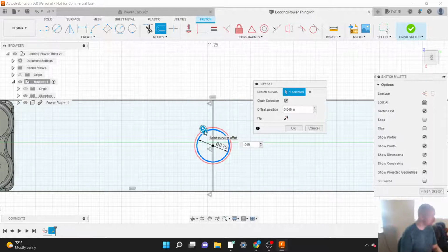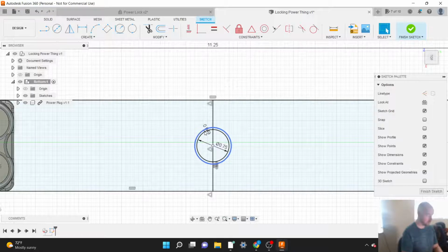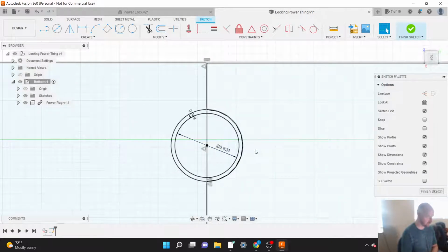Okay, 3/4 conduit has an official outside diameter of 0.922 and an ID of 0.824. Oh, so the interior diameter is 0.824. Yeah. Okay. That'll be close enough. So I think your wall thickness is still about 49 thousandths. Okay. Roughly.